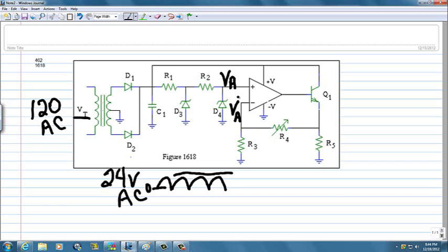Because the voltage is VA here, that means the voltage VA across R3, then the current through R3 is VA divided by R3. Let's call that I3. There's no current into the ideal op-amp, and so all of that current has to come through R4.